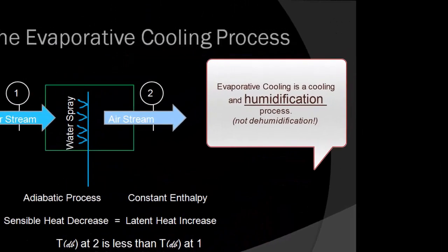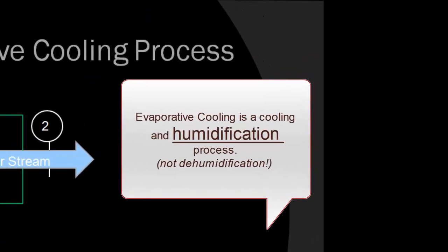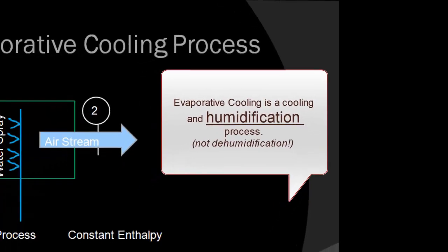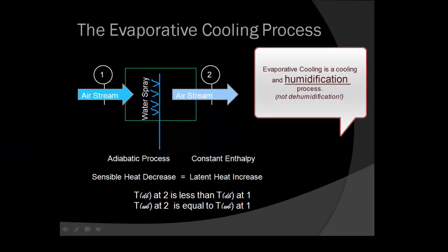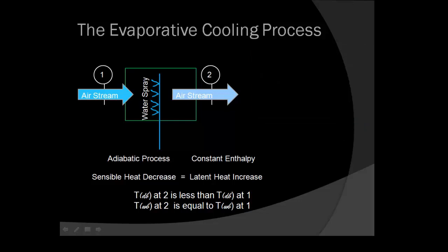Evaporative cooling is a very special cooling and dehumidification process that deserves a detailed discussion in itself. Evaporative cooling occurs frequently in air conditioning systems. Two noted examples are cooling tower applications and evaporative coolers. In evaporative cooling, a noticeable change occurs in the airstream. The dry bulb temperature of the air decreases even though no external cooling source is used.